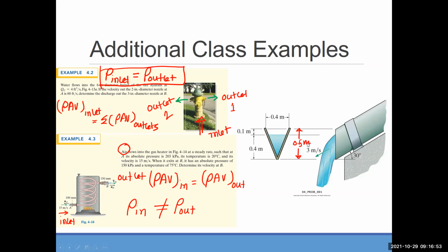But you can see the water is not up to 0.5 meter. There is an empty space, right? So water is up to 0.4 meter. So when you calculate the area, like Q equals to AV, that A should be just the area of water, okay?